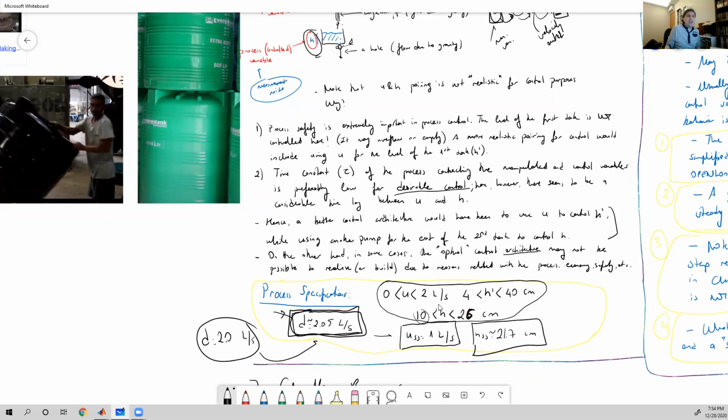If we would not be changing the set point of the process, which is the steady state height value of the second tank, we would not be needing a controller. On the other hand, during the operation, from time to time, I would say that, okay, now we need water at 15 centimeter level. Of course, for this specific process it probably doesn't mean very much, but in real processes they are going to correspond to more realistic variables like outlet concentration, temperature, and so on. So I think you can easily convert to a more realistic setting.